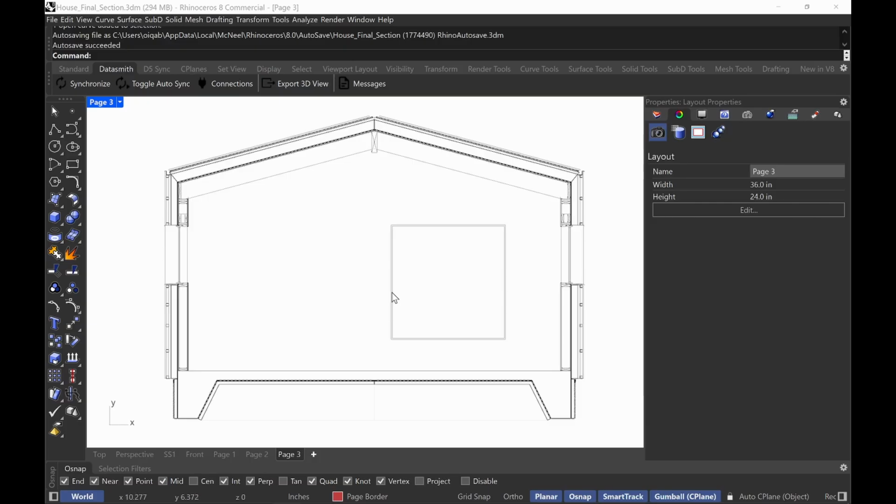And then mirror everything. And the same thing for hatching. Don't go in and start hatching everything at once. Just hatch half of this and then mirror your hatching. It's going to save you way more time, and it's going to be less of a headache where if you made a mistake or you catch a mistake in one side, you don't have to go back and redo everything all over again. So just do half of your drawing if it's symmetrical, okay? If it's not symmetrical, then yeah, you would need to go in and do everything. But if it is symmetrical, then just be very efficient and just do half of something and then just mirror it when you're completely done with it, okay?